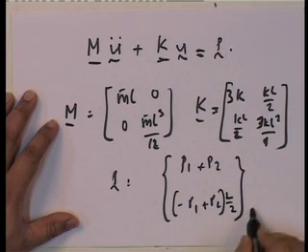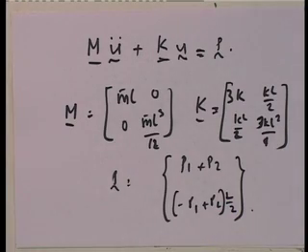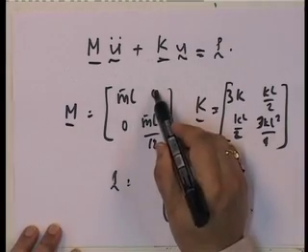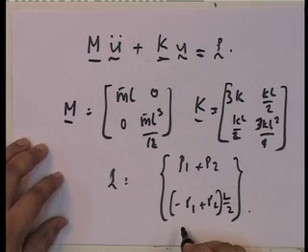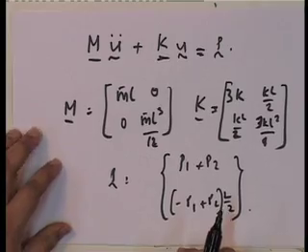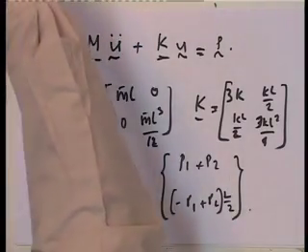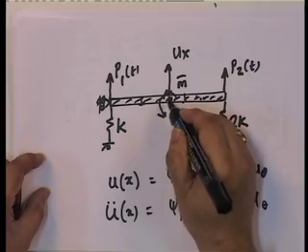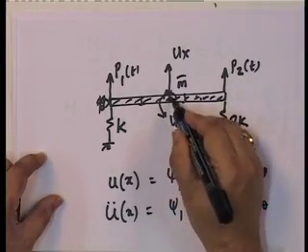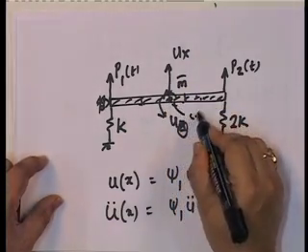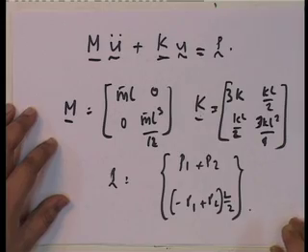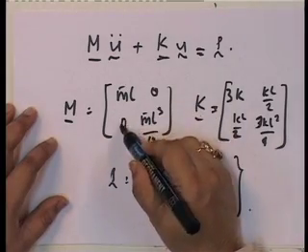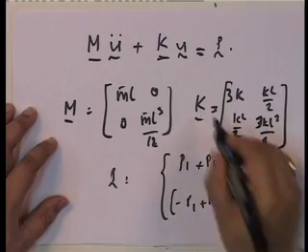Now, if you look at this, the mass matrix is a diagonal matrix. Why? Well, there is a reason. Because the center of the joint, if you remember, we defined the degrees of freedom here, which is also the center of mass. When you define equations at the center of mass, then the mass matrix always becomes uncoupled.